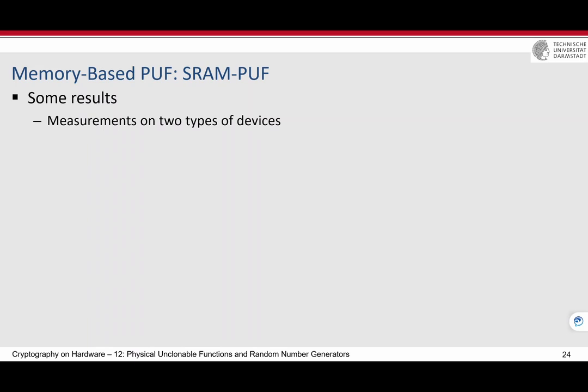For example, suppose that you have a 28 nanometer technology, and two lines or two pins should not be closer to each other than a particular threshold. Let's say not smaller than 100 nanometers, two lines. And then if you violate this, there is no guarantee that these two lines become completely separate from each other in the metal layer. They might be connected to each other.